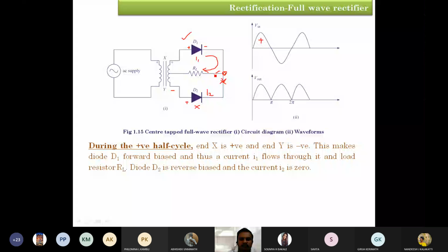Okay. So what is going to happen? For all positive input, we know the rectifier input voltage equals output voltage. For V in, diode D1 is going to perform its operation in forward bias condition. Therefore, the voltage across RL will be available with the amplitude value of V, between the duration 0 to pi, or generally the positive cycle of the input.